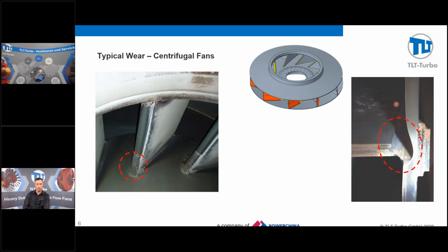You'll also see it on the pressure side, where you can see the wear plate on top of this fan blade itself. What's happening is the erosion line is coming down the pressure side of the fan in between the joint and the backing plate, and it's actually wearing through the weld seam and then working its way into a larger cavity on the trailing edge of that fan blade.